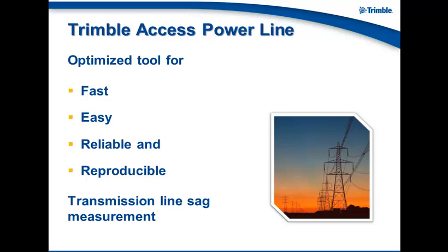To accomplish this, Powerline lets you easily measure key points on a power pole, like conductors, etc. It helps you create lines through those key points, which are rough estimates of your true cable. In the end, it will let you stake out the line elements with angle measurements, so you don't need a distance reading. The height gets adjusted via aiming at the cable after the total station has driven to the stakeout point. So the operator only adjusts the vertical angle of the gun. Everything else is done in software. There's a bit more to the workflow, but we will see this later on.